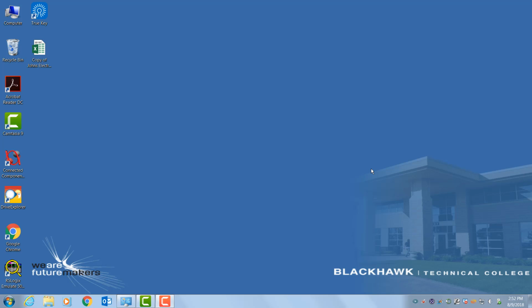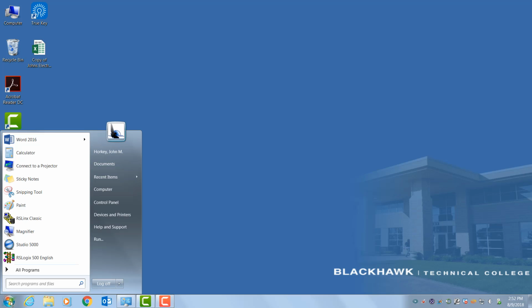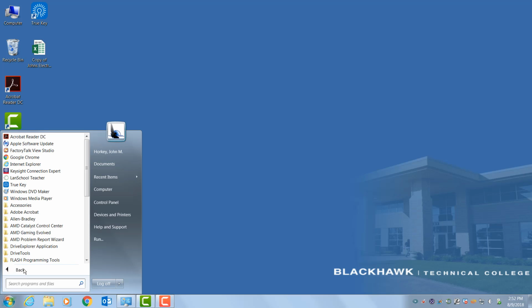In this video, we are going to connect an SLC 504 PLC processor to the personal computer, set up communications, learn how to download, and write a very simple program. This process uses two different software packages. Both are Rockwell software. If you go into All Programs and Rockwell Software,